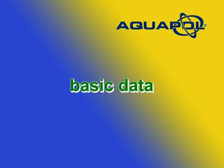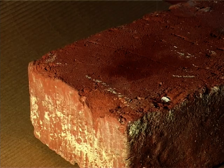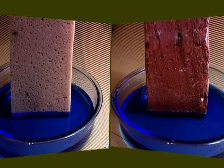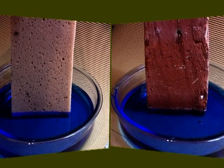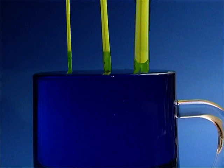Basic data. From building physics we know that water is absorbed by building materials like a sponge. This effect is referred to as the capillary effect. If we put two materials of different porosity into a water bowl, we will observe the following. Building materials with larger pores absorb more, while those with smaller pores absorb less. The thinner these pores are, the more capillary they have, the higher the water rises.